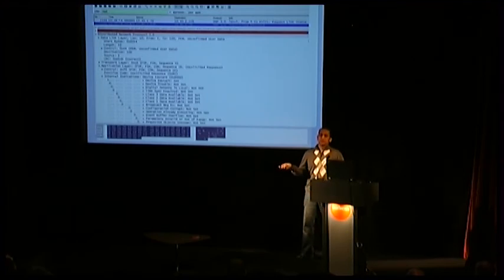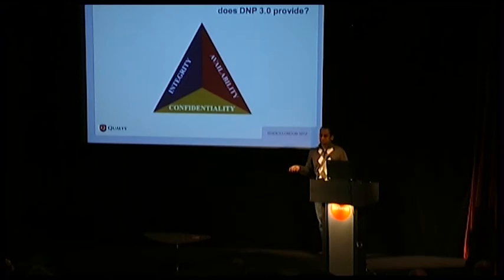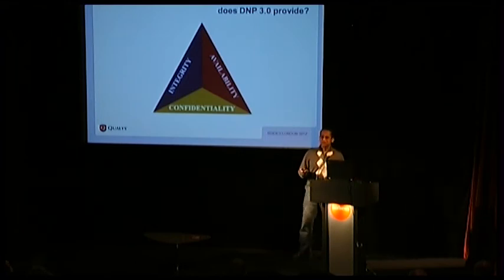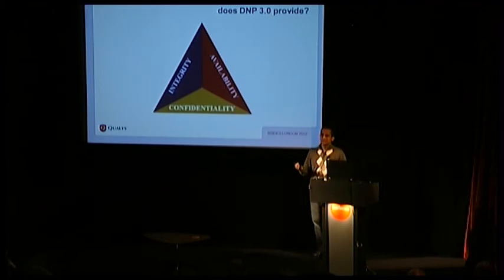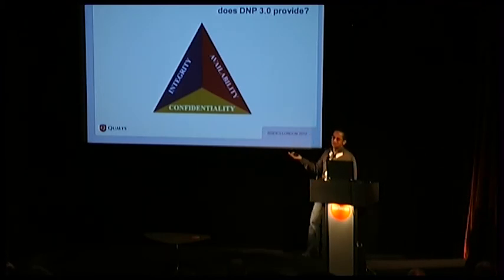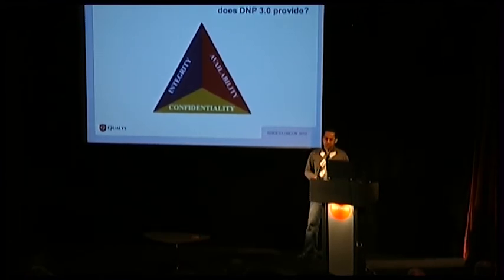Same question again that we asked for Modbus. What did it provide? Confidentiality, which has basically authentication? Not really, we didn't authenticate against the server. The server didn't ask us who we were. It just took our request and sent us the reply. No access control or authorization. Some integrity as part of the CRC, but as you know, it can easily be broken. You can have a lot of man-in-the-middle attacks, but still some sort of a CRC as compared to Modbus.